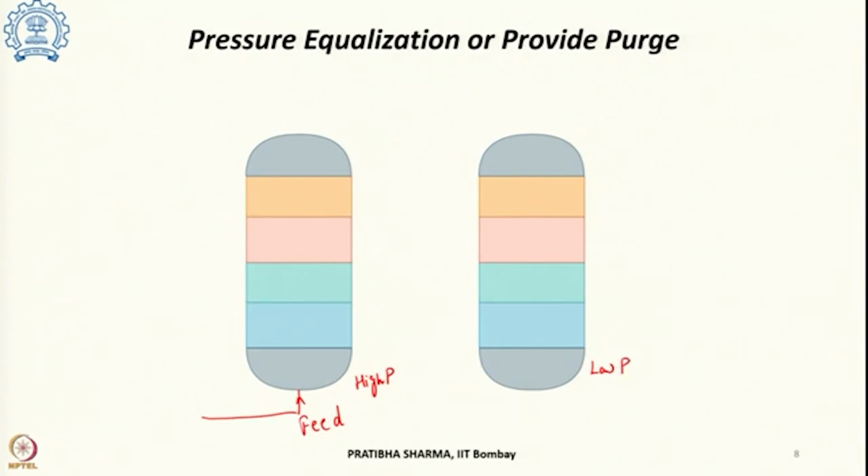So, before the blow down step, when the first step, the pressurization step, is operational, at the end of it there is still a large amount of hydrogen in the bed. The feed is stopped at that point and the gas flow from the high pressure bed takes place in the co-current direction of the feed gas.